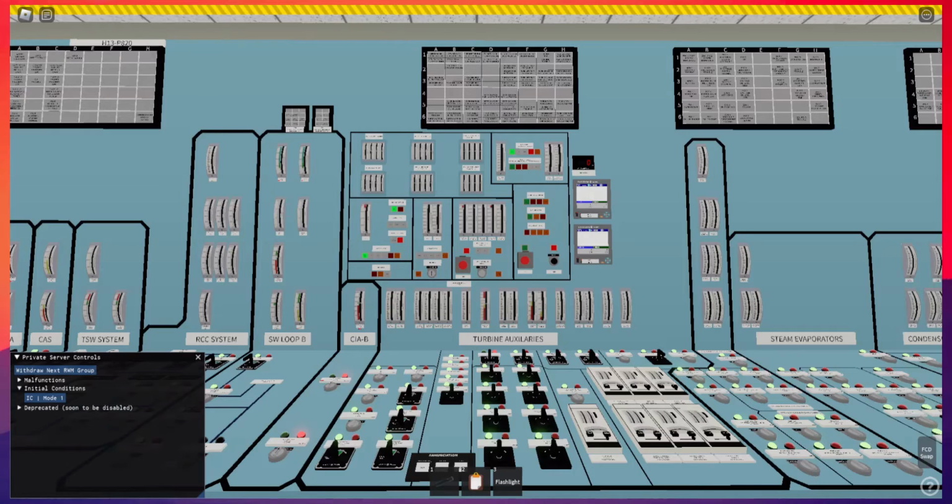That will be how many megawatts you want your generator to make, the speed set point or the speed match for the turbine, as well as the bypass valve, as it's commonly known, as well as pressure hold and some mechanical and electrically related trips in the turbine.